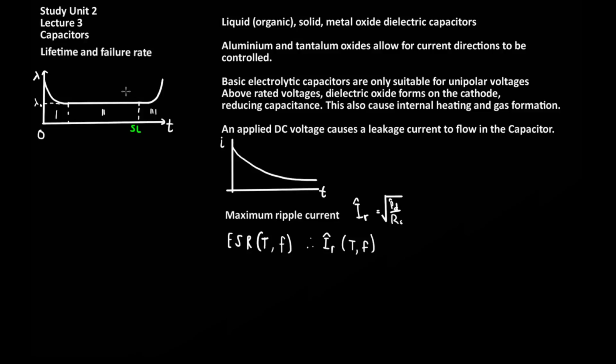There are several ways to increase the lifespan of a capacitor. The first is to operate the capacitor at a lower ambient temperature. The second is to decrease the ripple current or ripple voltage through or across the capacitor. The third way is to lower the operating voltage across the terminals of the device relative to the maximum rated voltage. And lastly, the higher the AC frequency across the device, the lower the load will be on the device, and thus the lifetime of the device will be extended.